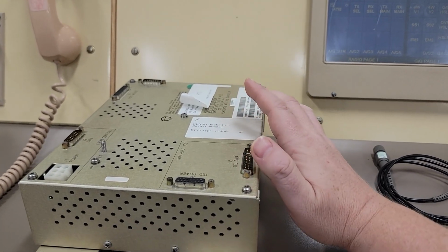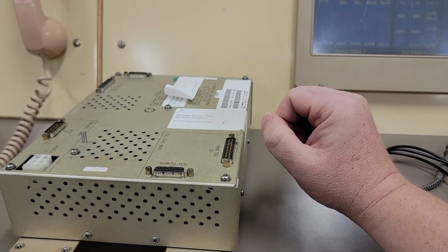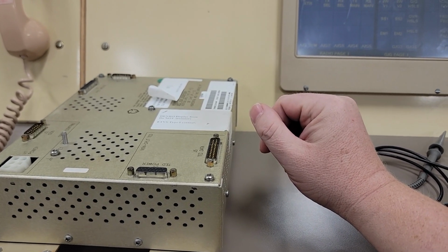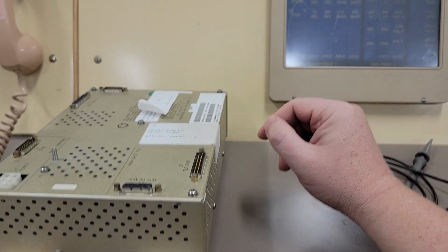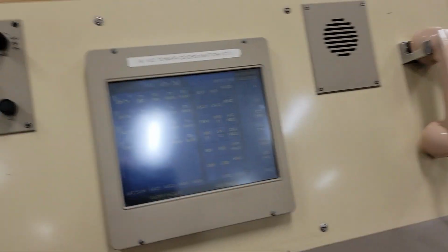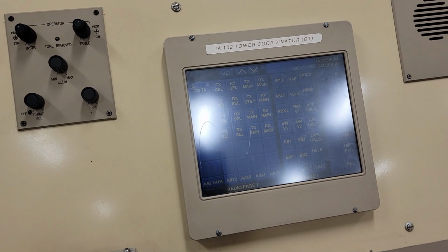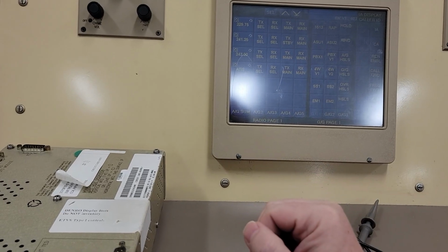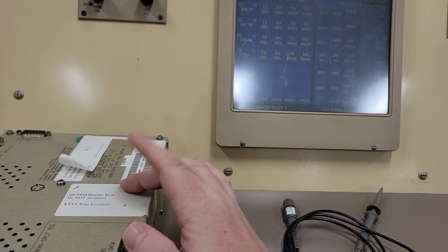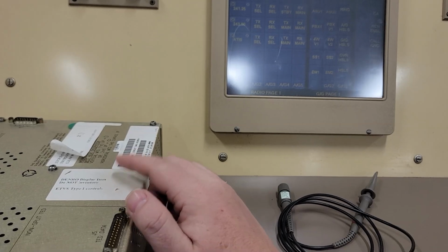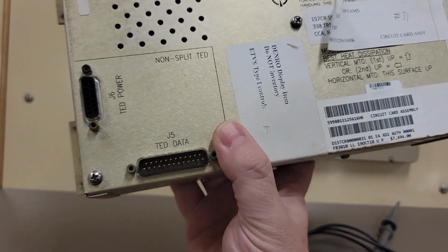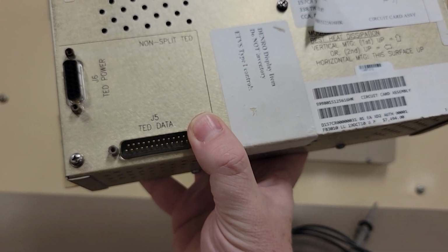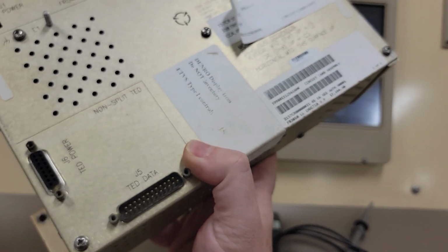Now, the way this video feed is used is very similar to older medical equipment that made use of a KVM, say a little device set beside your bed that measured your heart rate and so on. There'd be a device and then a cable going to the monitor. It's old monitor technology. You're going to have red, green, and blue over a DB25 cable. Yes, that's DB25. Typically, you would refer to that as a serial data cable, but not in this instance. It's being used to provide multiple video feeds and horizontal and vertical sync.